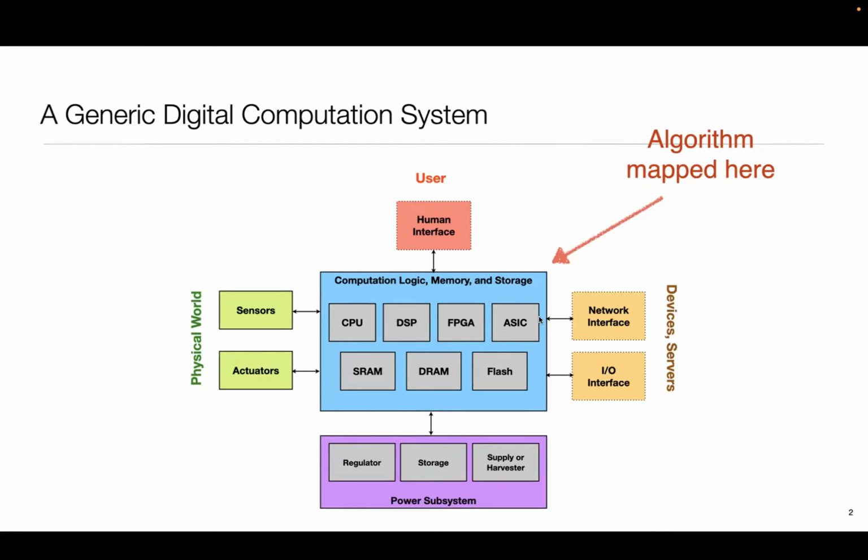So the same thing, let's say I'm trying to add up a bunch of numbers, right? On a CPU, it might look like a for loop with a variable in which I'm just accumulating those values. Whereas on an FPGA or ASIC, it might look like an adder hardware with hardware to store the values, and then we are looping through it in hardware. Okay, but conceptually, it is really an algorithm being implemented either directly using the gates or indirectly using a processor, which in turn, of course, is built using those gates, right?